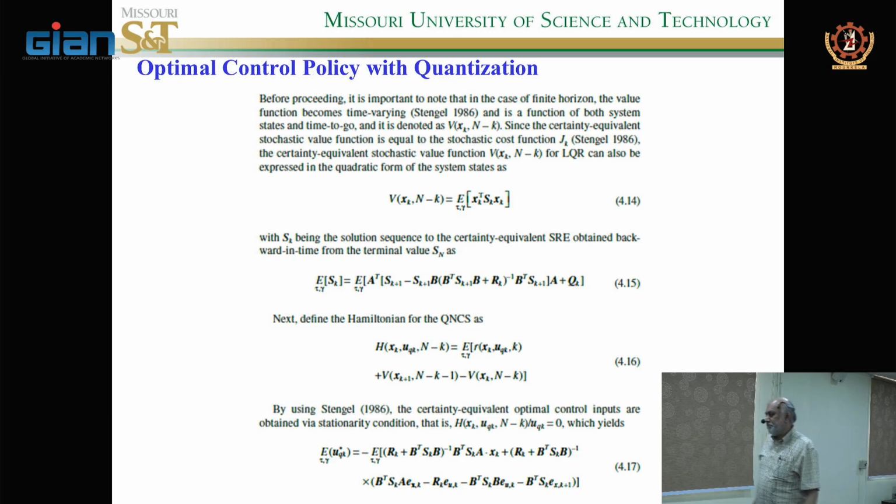Go ahead. Another thing, about the dynamic quantizer: it is multiplied and then divided, and then they adjust the division. They crank up what's called the zoom parameter. So if you have a value outside the saturation range, by cranking up the zoom parameter you scale it and push it inside the saturation range of the quantizer. It changes things overall, but it still works, and I'll show you. It is better than the saturation. That is correct.